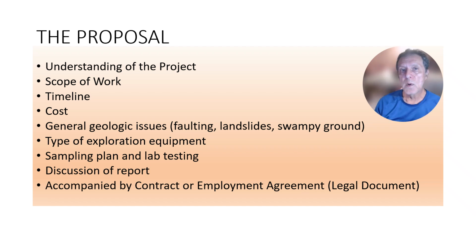You have to have a sampling plan for extracting samples and types of samples. Maybe you want to do California split spoon samples or standard penetration test samples, or maybe you want to do cone penetrometer type sampling, or maybe hand sampling from a backhoe. What sort of sampling plan you're going to have, and what kind of lab tests are you going to perform on these extracted samples. Put that into your proposal.